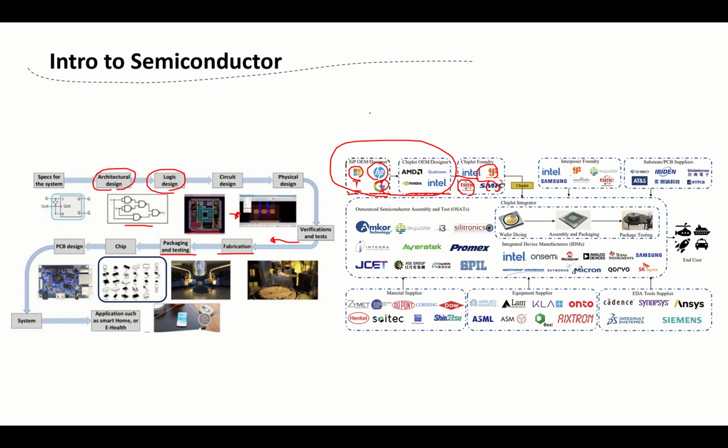So how does that work? We have an interposer over here, and here's a PCB. We have C4 bump, RDL, and TSV, and RDL again, then C2 bump, then we have the CPU and HBM. We'll see the CPU and the HBM are really close. We're packaging them on one chip, so we can improve the throughput and reduce the latency to make the device faster.